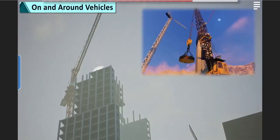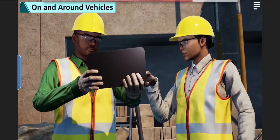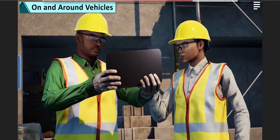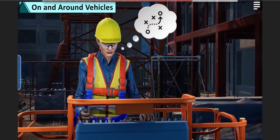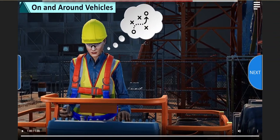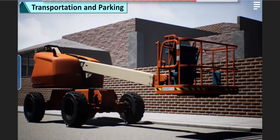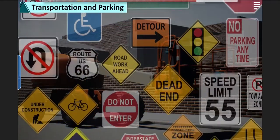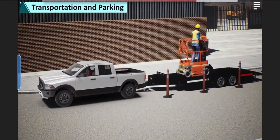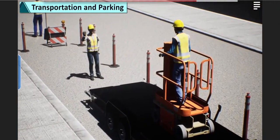If the MEWP will be operated in conjunction with another piece of moving equipment, such as a crane, the operation must be properly planned with a system to coordinate work and communicate between equipment operators. The operator must have a plan for dealing with foreseeable contingencies and emergencies. If the MEWP must be driven on a public road, take all necessary precautions and obey all applicable state and local traffic laws. If the MEWP must be unloaded from a transporting vehicle on a public road, take precautions to protect the people involved and alert the public.